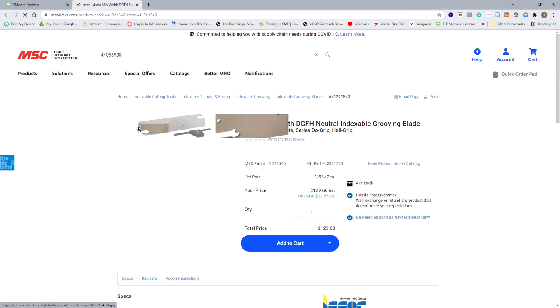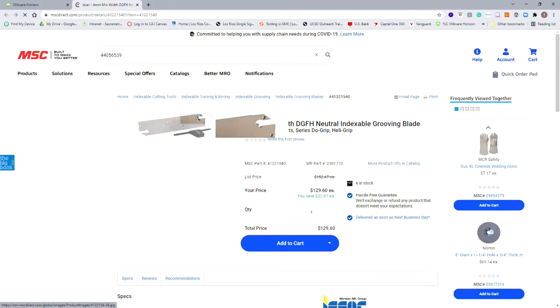So it's this flat blade looking part, and the insert gets captured in here, and it can be used almost like a single tip saw. As the material's turning, it'll cut the material off. And it has two sides, so when the one end is worn out, you can flip it over. And the insert that goes in there also has two sides, so you really have 4 cutting edges you can use before this thing's worn out.